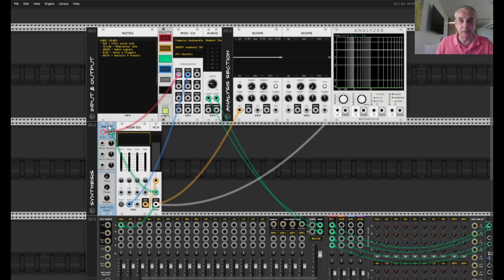I have some baseline knowledge about aliasing in sound, but also in image synthesis. So in computer graphics, you also have aliasing effects in many ways, shapes or forms. Most noticeably jagged edges on graphics. The diagonal line is blocky in theory because you have pixels, but there is an aliasing theory behind it, which also has to do with sampling and reconstruction of a not band limited signal. Again, let's stop with the theory. Let's see how you can do that in the Saw VCO and get rid of some type of aliasing.